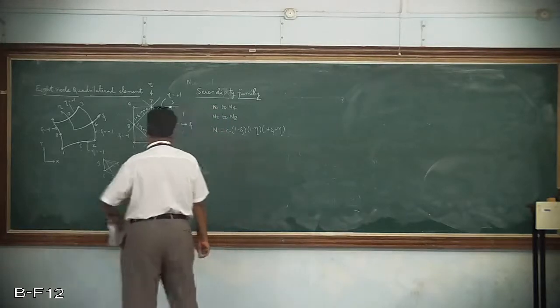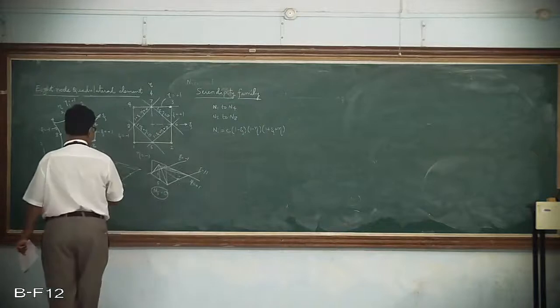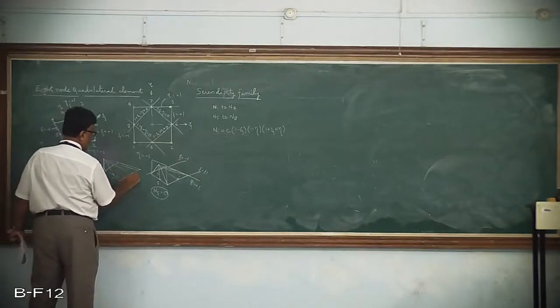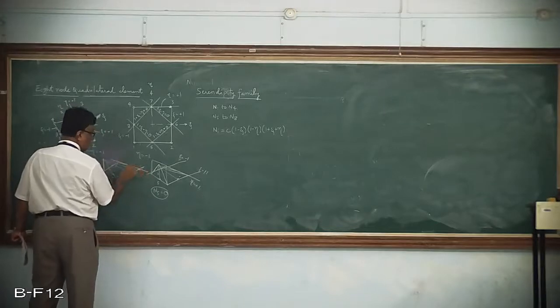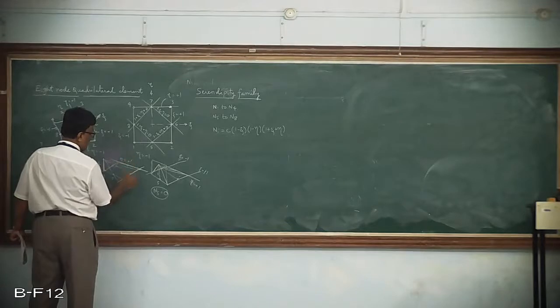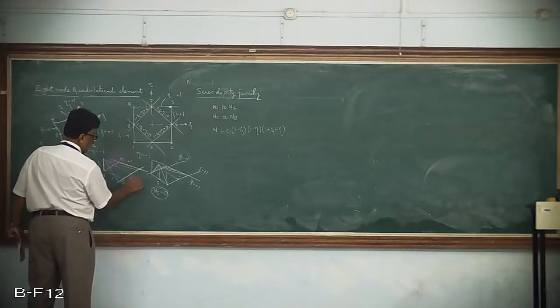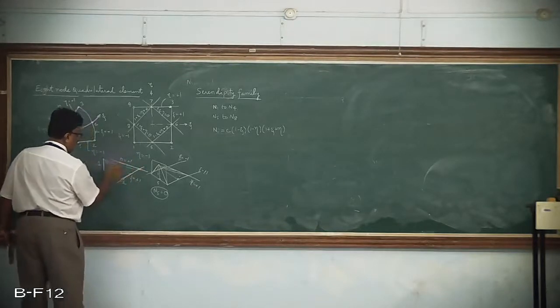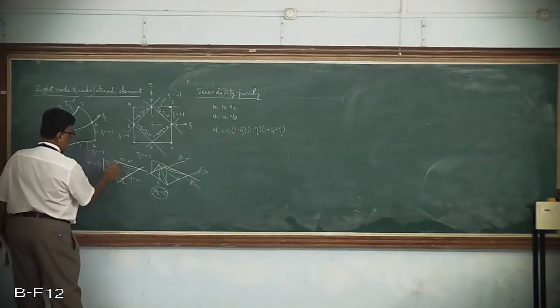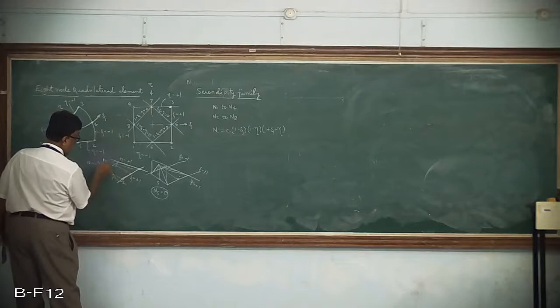Yes, see what is the meaning of this? If you look at this, n1 is 1, whereas along this edge and along this edge it is 0. That means this is zeta equal to plus 1, this is eta equal to plus 1. So along these two edges, obviously n1 is always 0. Remember, otherwise it is not 0, there would be a continuous variation here, that is not possible.